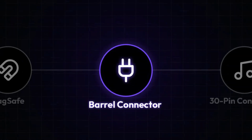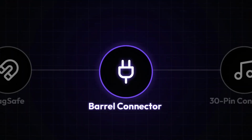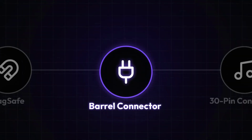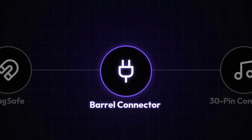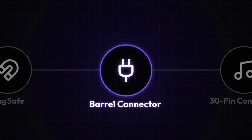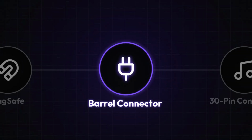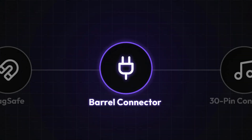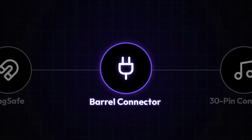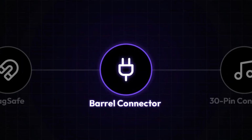Barrel connector. This cylindrical plug is a common sight on power adapters for laptops, routers, and household electronics. It originated as a simple way to deliver direct current power without the complexity of data pins. What makes it different is that it comes in dozens of slightly different sizes, requiring users to match the exact inner and outer diameters. It is still popular because it is incredibly cheap to manufacture and very reliable for devices that stay plugged into a wall constantly.